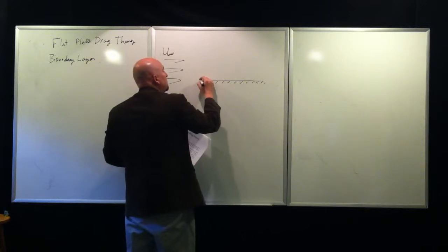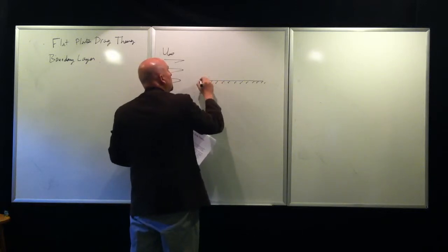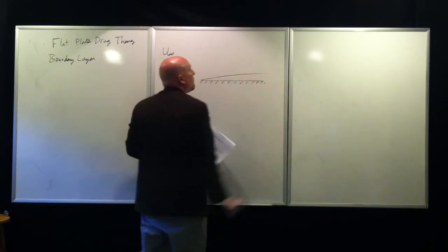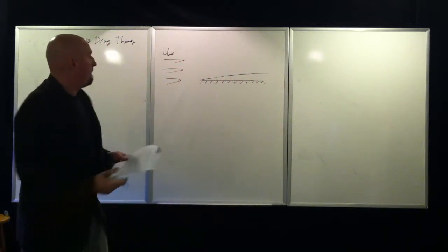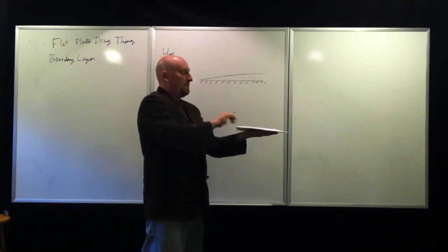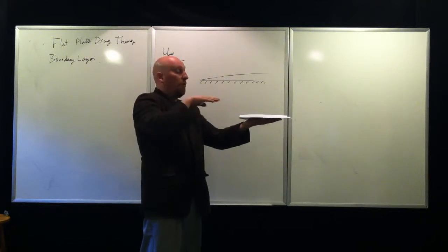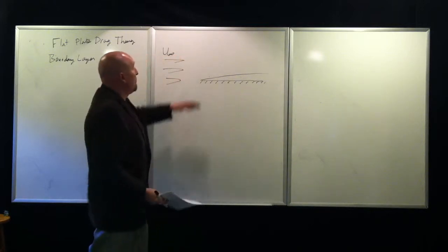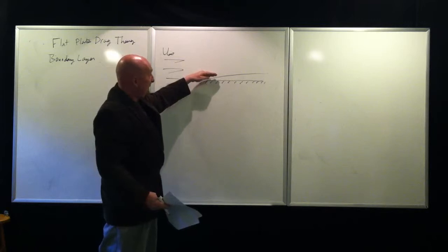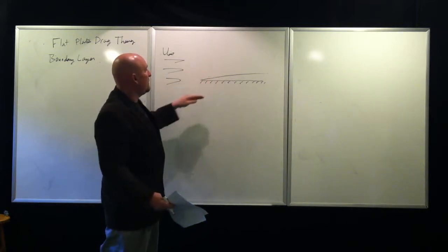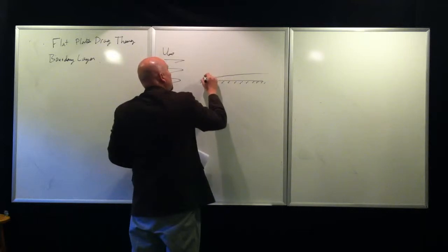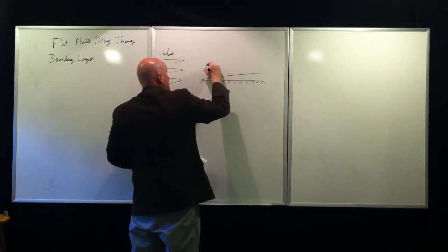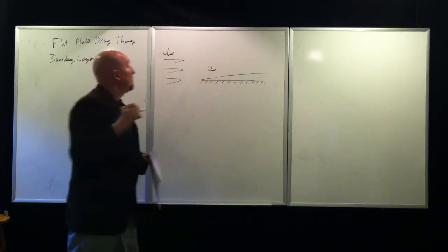If we represent this, we're going to call this a boundary layer. If you have a flat plate, such as this paper, air or liquid or water going over it, we're going to have what we're going to call and define as a boundary layer. Boundary layer is going to be a layer that is going to be a boundary between where you make the assumption everything out here is going to move with a free stream velocity of nearly the free stream.